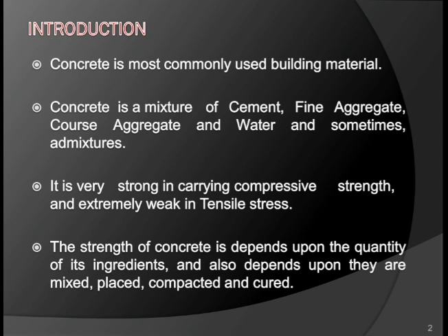No, the way the concrete is mixed, the way it is placed on site, the way it is compacted and cured, these 4 processes play an important role in gaining compressive strength of concrete. So the strength of concrete is not only the strength of the ingredients but also the process by which the concrete is placed in a particular component.